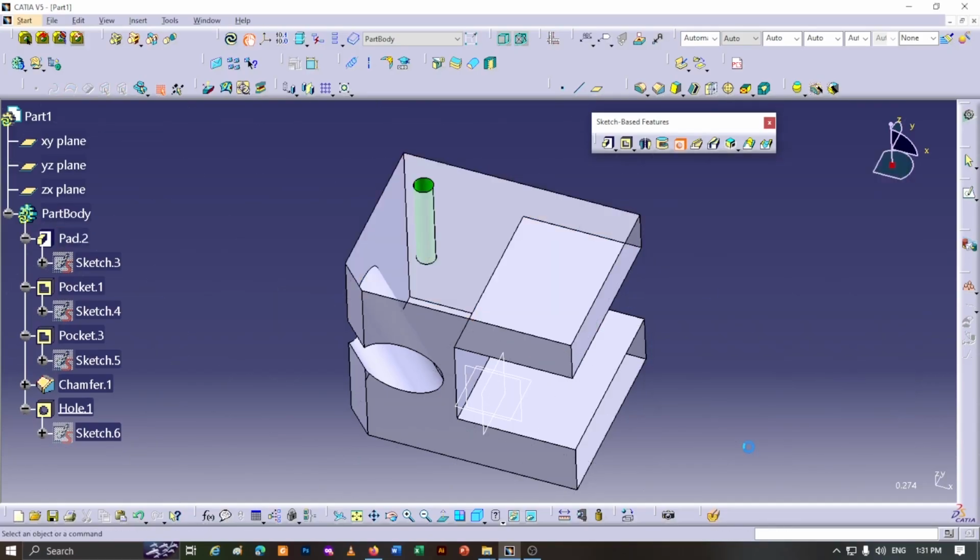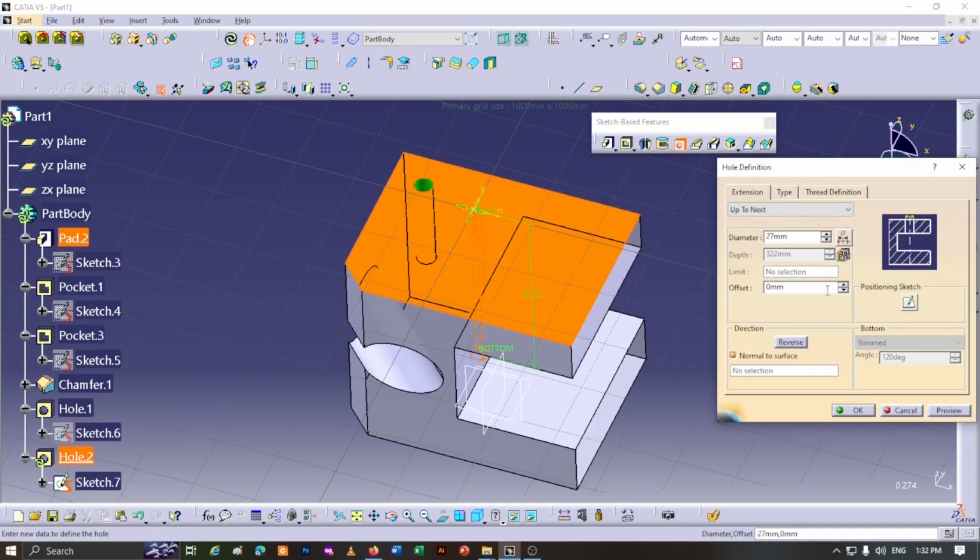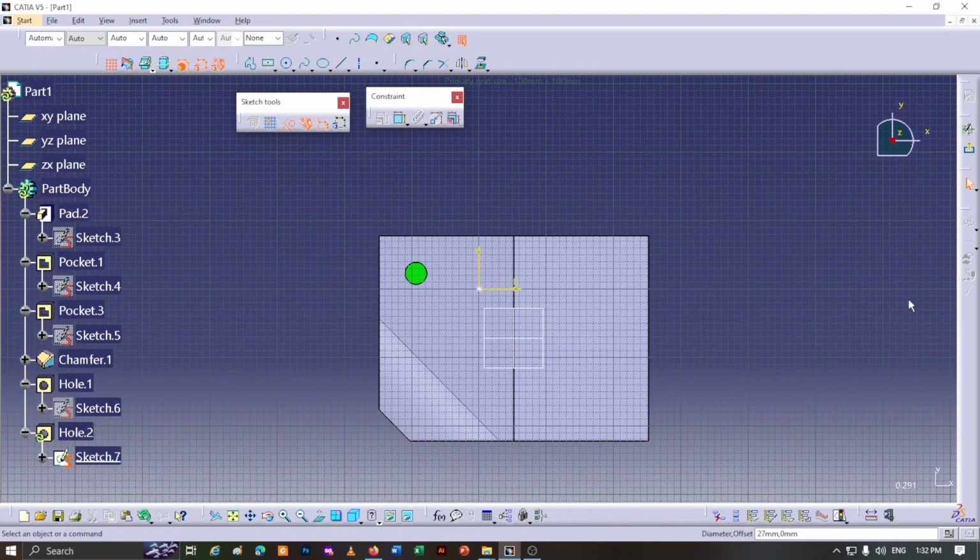Look, so far we have only specified the diameter and depth of the hole, but we must always specify the location of the hole creation as well. To do this, in this state where we see the hole, we click on the Positioning Sketch command. We are transferred to the sketcher plane. On this plane, the center of the hole is shown as a point. I place my mouse pointer over it. You can see it. Now I click on the Constrain command.